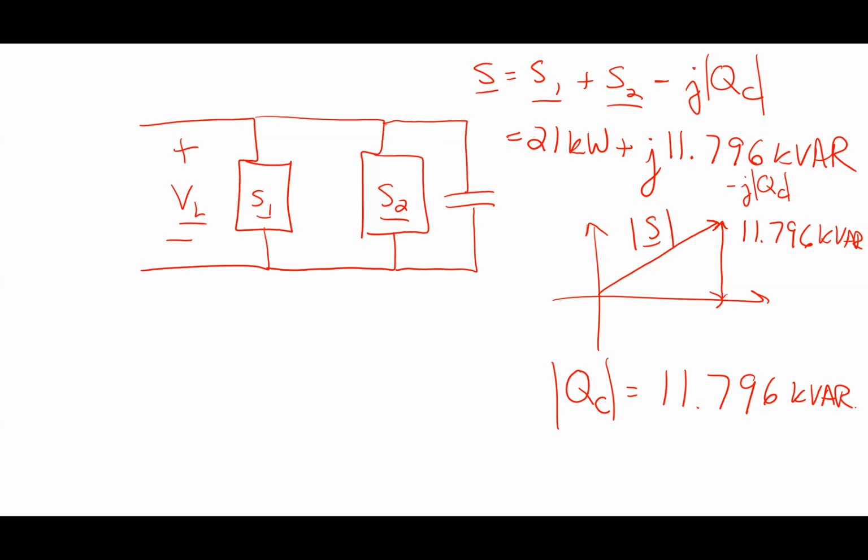If I put that capacitor bank there, it will keep the current coming down that line from Duke lower. There's not naturally a reason for you to put a capacitor in there, unless Duke gives you a penalty for saying, your power factor is so bad, you're making me shoot more current down there than you need, and that's causing me to burn more fuel. So if your power factor is too low, they're trying to incentivize you to fix it, so that they can reduce their costs. We'll look at that more.